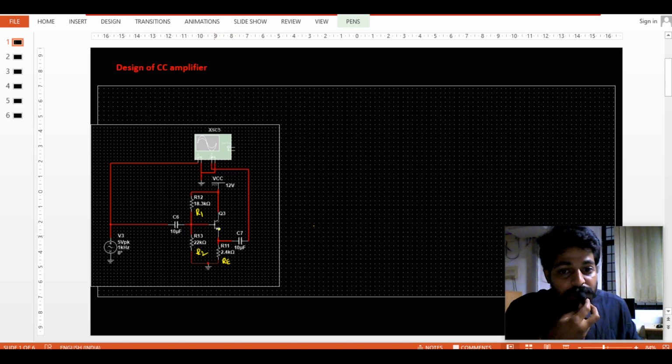So which we are connecting over here for the transistor circuit in the format where I give input at the base terminal. This is my base, and I collect the output across the emitter terminal. The collector terminal over here is common. So we call this a common collector arrangement where the R1 and R2 network are giving the biasing, and I take the output across the emitter terminal.